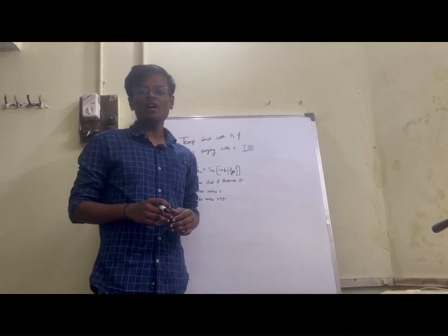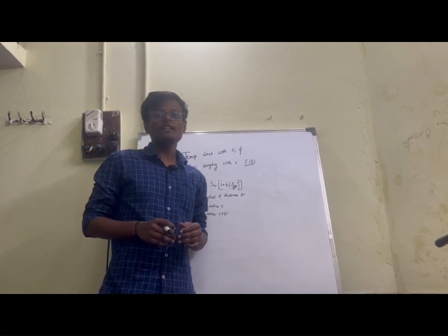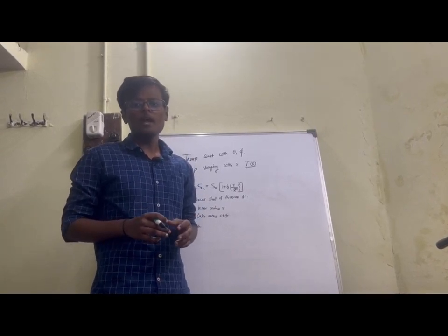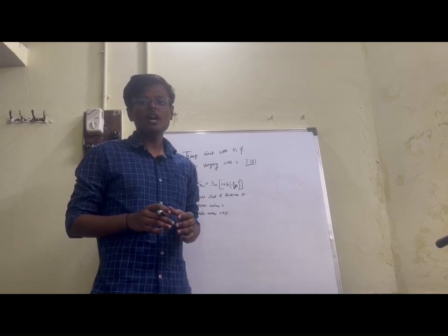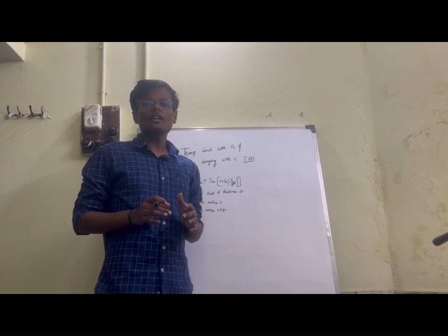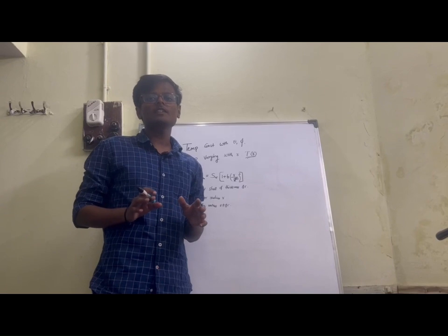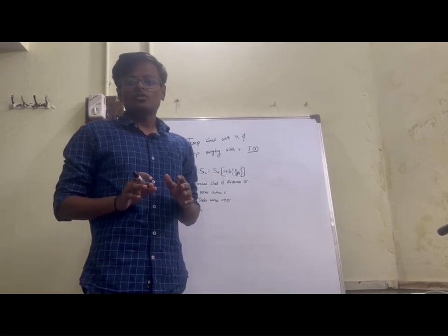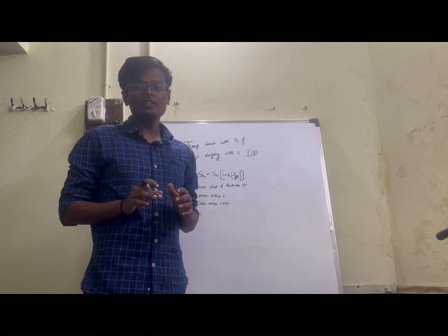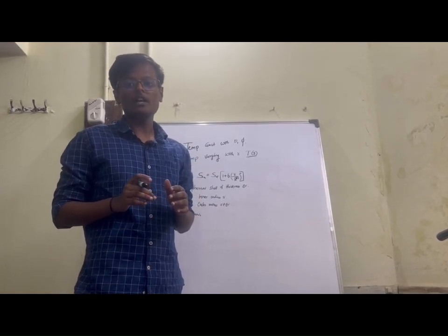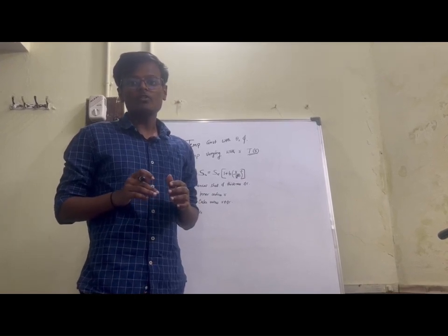So how do we figure out how the heat actually travels outside? A shell energy balance. Imagine this spherical shell. It has an inner radius of r and an outer radius of r plus delta r, a small change in radius. Shell energy balance basically says the amount of heat flowing into the shell plus the heat generated within the shell must be equal to the heat flowing out of the shell.